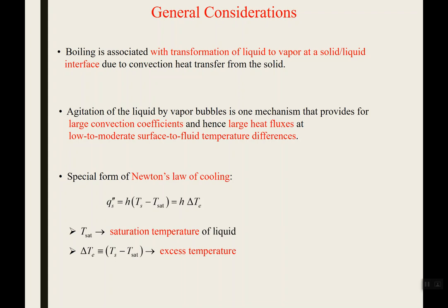So what did we learn about when we talked about laminar versus turbulent flows and convection? Which one, between laminar and turbulent, tended to have the higher heat transfer rates? Turbulent, okay, why turbulent? Eddies create mixing. Okay, great. So Kyle's saying that eddies create mixing. So as that turbulent flow starts going, it's agitating the fluid. That mixing is a really good thing for heat transfer if you do want heat transfer. So that agitation and that bubbling and boiling tends to make heat transfer coefficients pretty high when you're talking about boiling. They're also pretty high when you're talking about condensation.